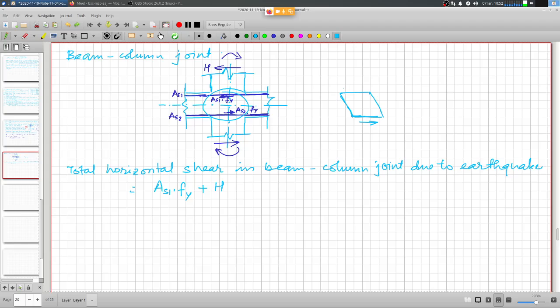And this is the behavior that you will see, a critical element of design in the case of steel buildings. So this panel zone behavior is very critical, and it has to be adhered to. It is under the influence of shear force, and it is under compression, and tension we disregard, at least in the case of concrete.